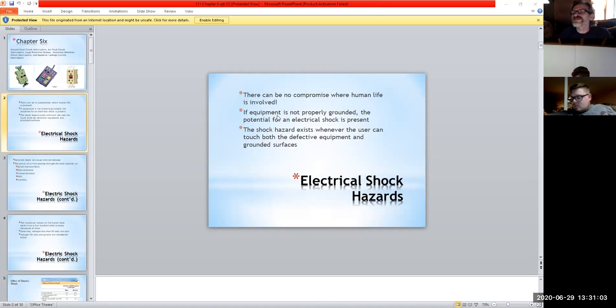Like all the ones that you're planning to plug the vacuum cleaner or any extension cords into. They make them in both circuit breaker styles and in a receptacle mount, so you could literally have an AFCI receptacle mounted in place in given areas too. It all depends on what kind of protection you're going for.